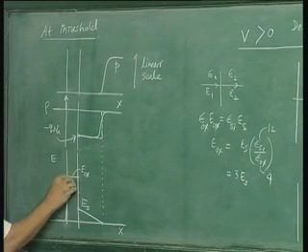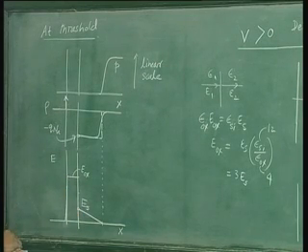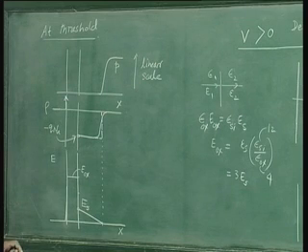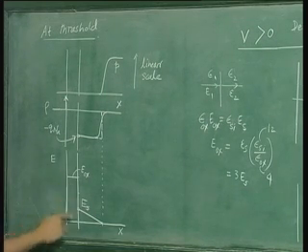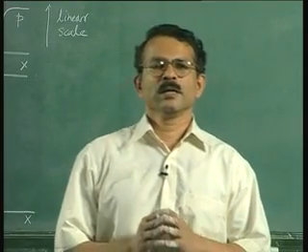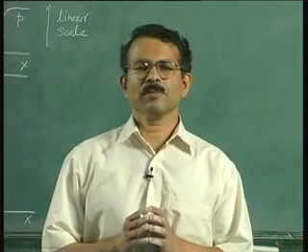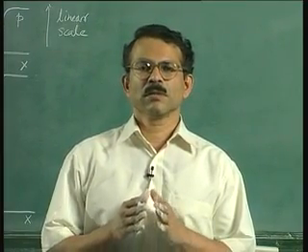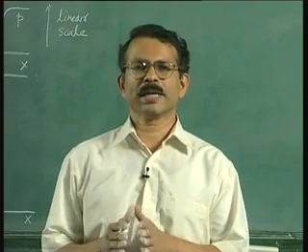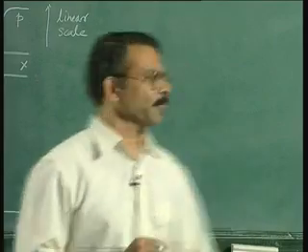Now this area under the electric field distribution is the applied voltage, and that is the threshold voltage. So to know the threshold voltage, we need to know this area. Now let us identify the components of the applied voltage across oxide and across semiconductor on the electric field versus X diagram.